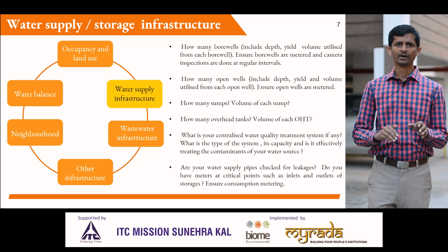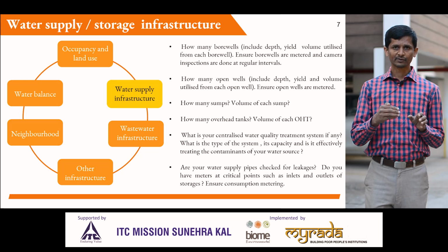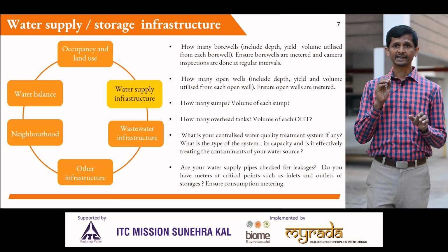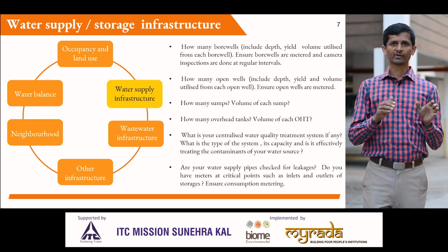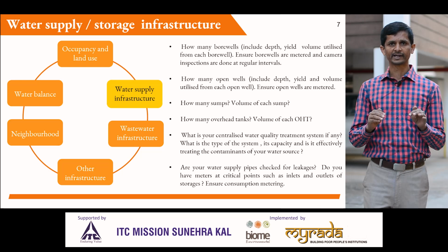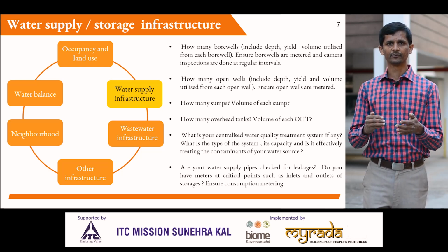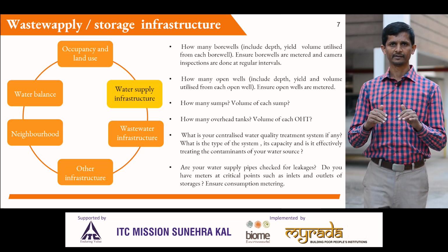of water. Also identify if there are any leakages in the storage structure and in supply pipes, which is essential to know what the real consumption is. Ensure your water quality system is not an overkill and water quality is monitored regularly at the source level too, in addition to water quality monitoring before the supply.